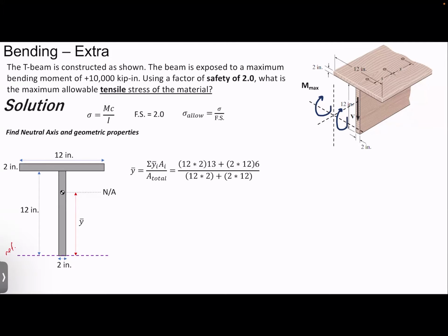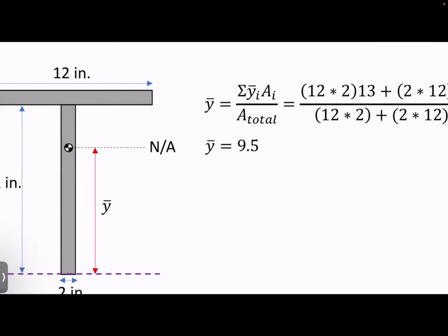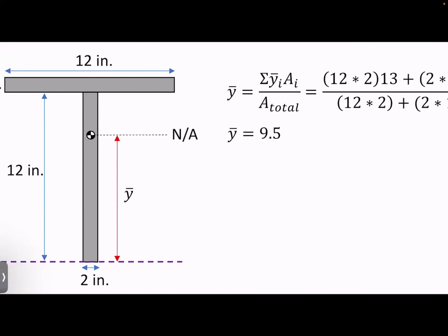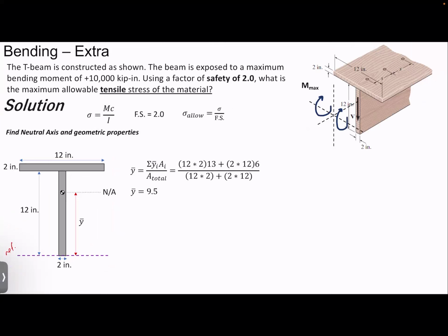All this is saying is we divide it into individual rectangles on the numerator. So that's that sigma, that summation. Each one of those individual rectangles, we know where the centroid is. I'm about to draw on this anyways, but we know where the centroid is with respect to that reference axis. So we take each individual centroid and then we multiply it by the individual area.